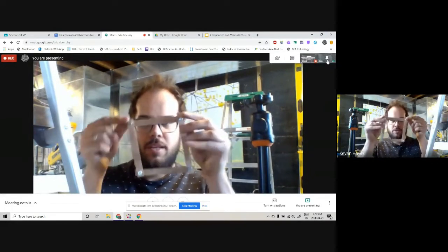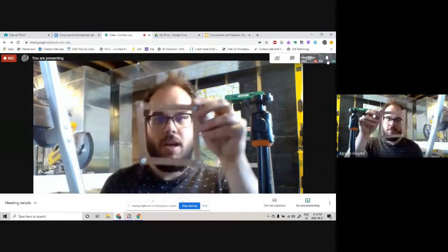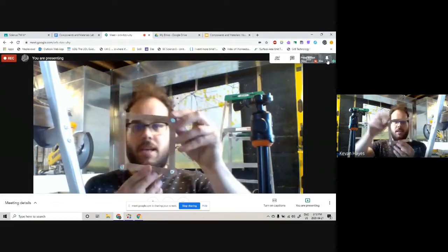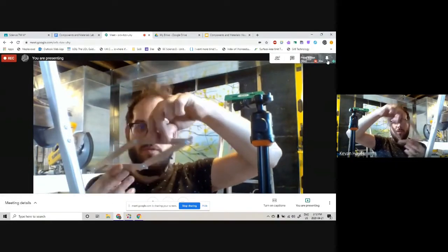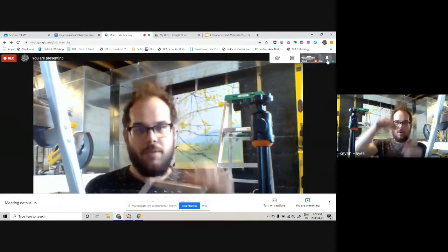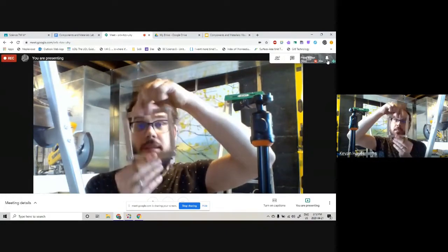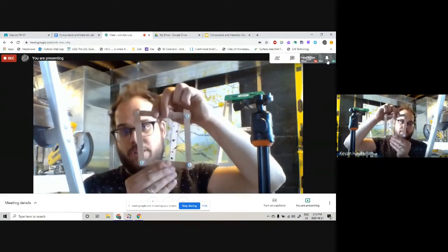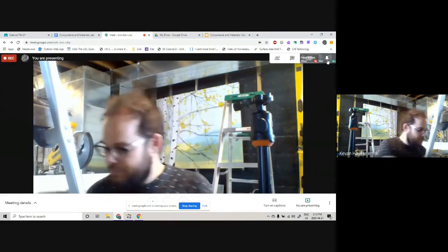Each of these screws is what we call a joint, and we'll call these parts the members of the square. And even if the members are strong, if the joints are able to move, then this structure is going to move. Now, you might want that to happen, right? There are some structures that have moving components, and they do that deliberately. But if you don't want this structure to move, then you really need to pay attention to what's happening at these joints.